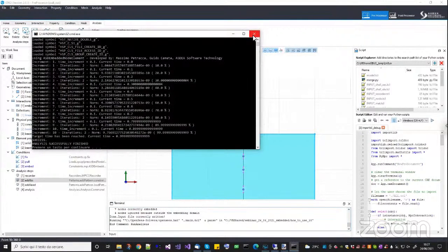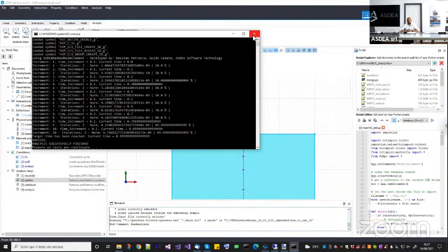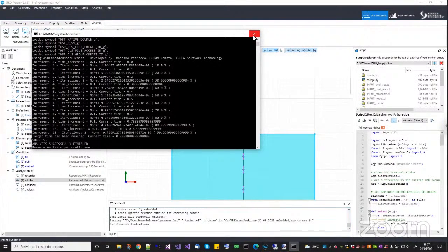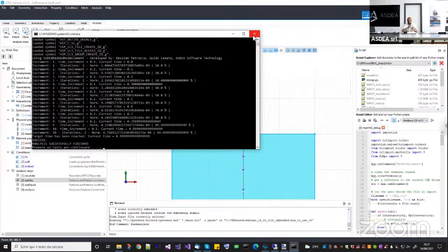Massimo? Yeah. Can I ask you a question? So the skew symmetric part, the rotation, is also the rotation of, like, if you consider the face, it's the average rotation of the face of the four nodes, right? Not actually, because in this case, the face does not have rotational degrees of freedom. But actually, you can compute the rotation from a displacement field. Yeah, so the rigid body rotation of the plane, right? Exactly. Interpolated at the point it falls into.